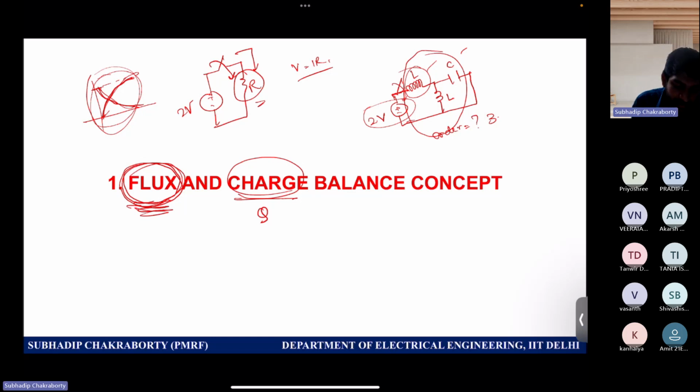These two things help us in determining the voltage for the capacitor and the current through the inductor, because we always write that the current through an inductor, IL, since an inductor is a linear element, cannot change instantaneously, a very popular statement in electrical engineering.